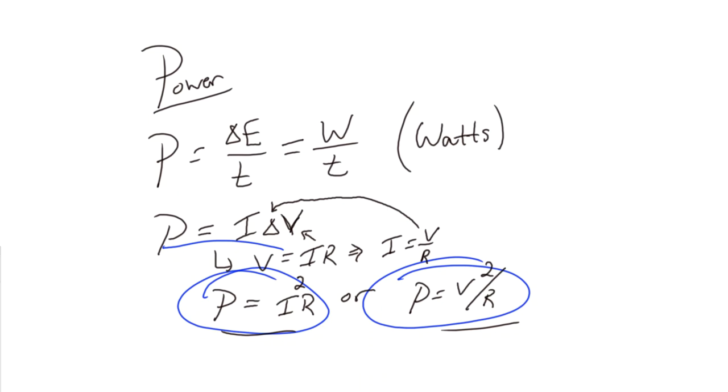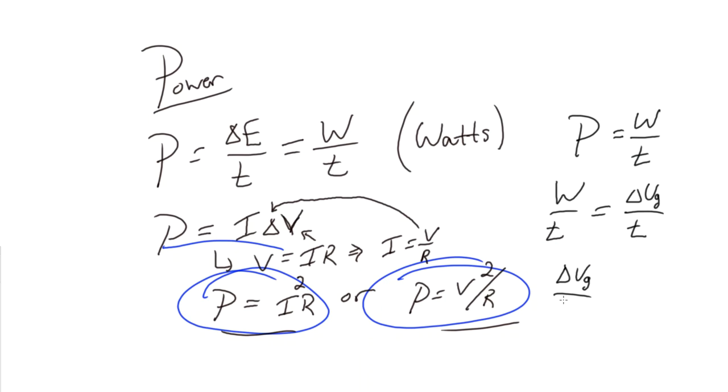And so what we got here is, if we look at power being work over time, if a motor is in place, we could look at its work being usually a change in gravitational potential energy over time. And so then from there we can set this equal to current times your potential difference, or voltage. All we're saying is mechanical power and circuitry power have a role to play with each other. Depending on how you need it, you can change those variables around. But those two definitely interact.